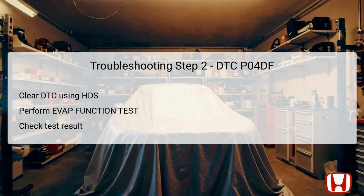After preparing the necessary information, the next step is to clear the Diagnostic Trouble Code using the Honda Diagnostic System, HDS. This system allows for the resetting of stored codes, which is vital for determining if the problem is ongoing or if it was an intermittent issue. Following this, the technician should perform the EVAP function test found in the inspection menu of the HDS. This test specifically checks for proper operation of the EVAP system components and can provide immediate feedback regarding their functionality.